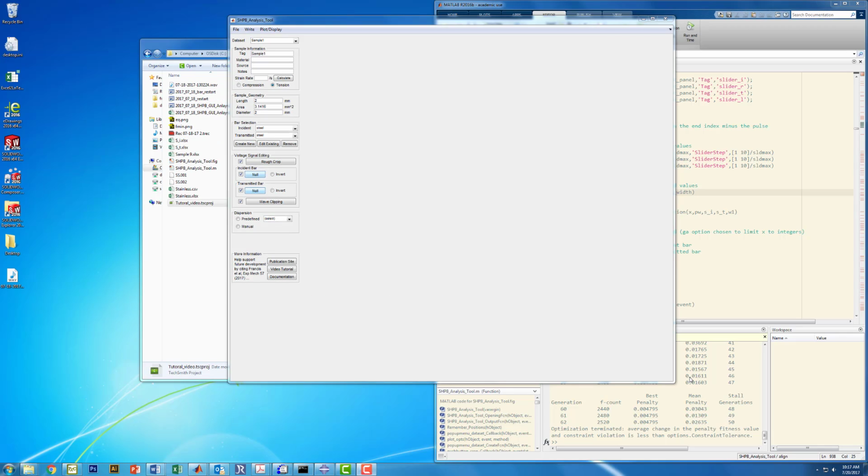One last thing I forgot to mention is there's an option to calculate your strain rates. Again, with dynamic testing, it's really hard to say. You don't have a constant strain rate. It's not like you're running just a quasi-static test where you really can control your strain rate. This is dynamic testing. So with that in mind, there's this button here called Calculate by the strain rate box.